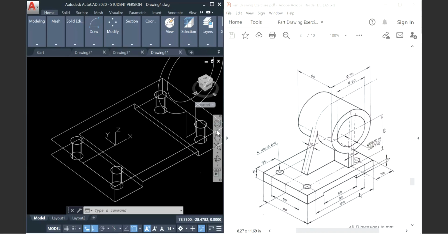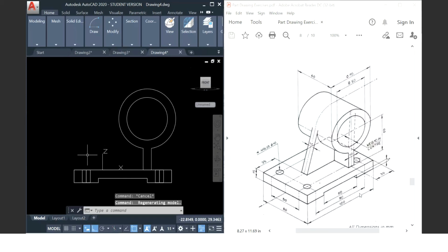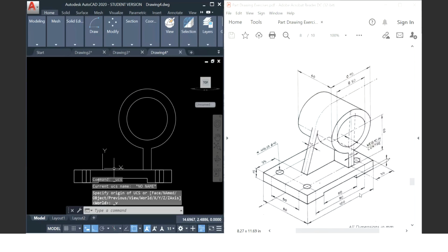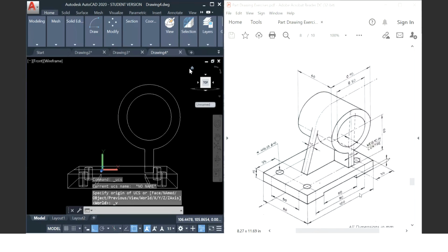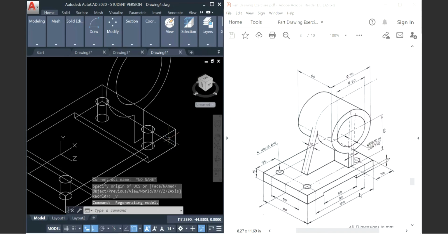So now, if I look at here, this is basically the plane I want to construct this geometry on. So I need to make sure this plane becomes my XY plane. Right now it is not on my exact plane. I need to change it, go to coordinates, go to view, make view, so that I change it to become my XY plane. So that now I can construct my object.